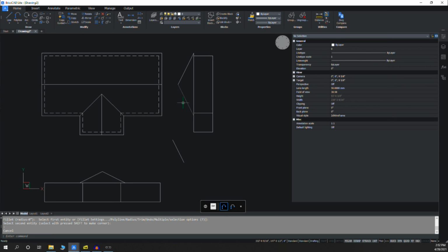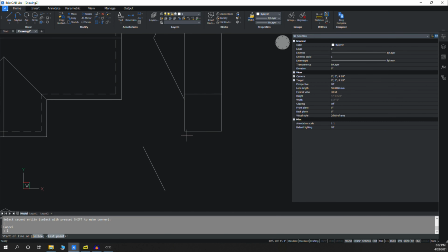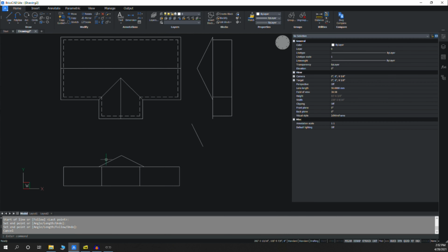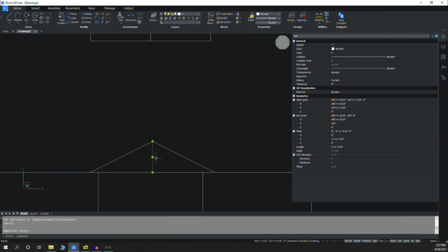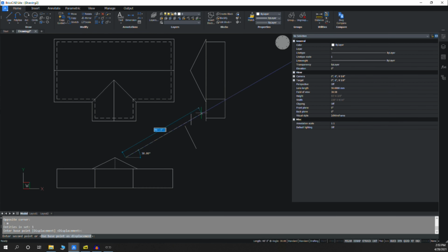this front gable intersects on this roof. Remember, don't forget your 18-inch eave here. And I'm just going to make, let's do the measuring stick. So we're going to make a measuring stick from here to here. And then we're going to grab this to figure out how high this roof would be in this other view. So there we go, got that there.